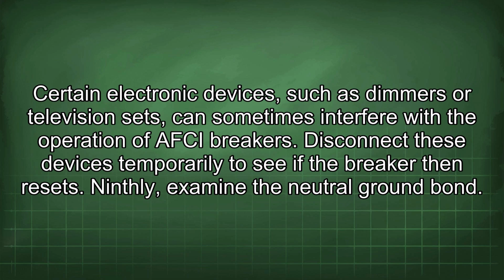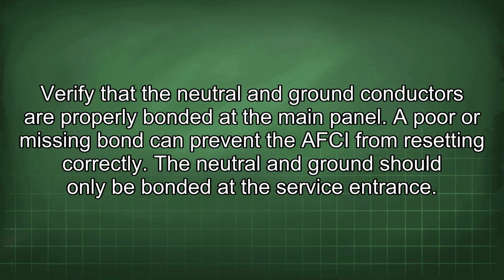Ninthly, examine the neutral-ground bond. Verify that the neutral and ground conductors are properly bonded at the main panel. A poor or missing bond can prevent the AFCI from resetting correctly. The neutral and ground should only be bonded at the service entrance.